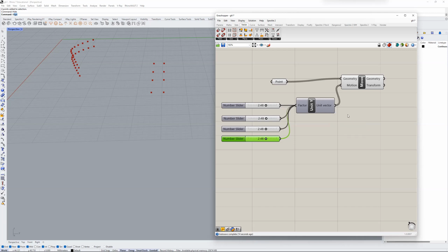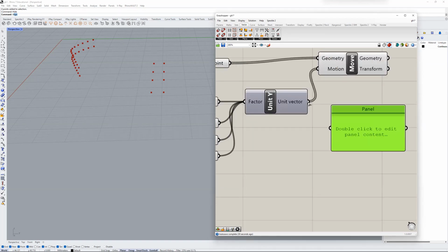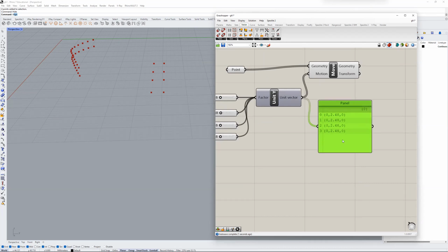defined values. And I'll introduce you now to another very useful component, and that's called a panel. You can search for it. It's right here, panel. There's also a shortcut for this. You just do // and that gives you a panel. And that lets you see the output. So if we hover over this, we can see the same thing, but this gives you more detail and the ability to scroll when there's lots of data.